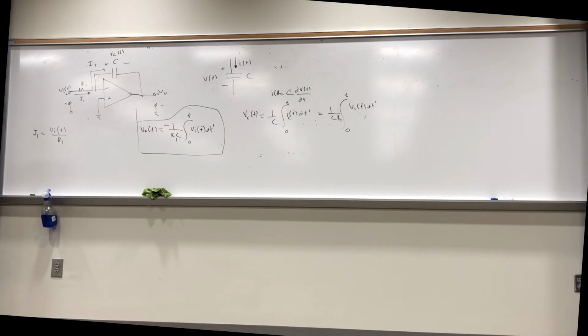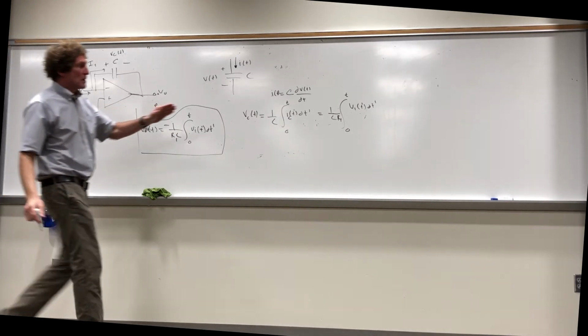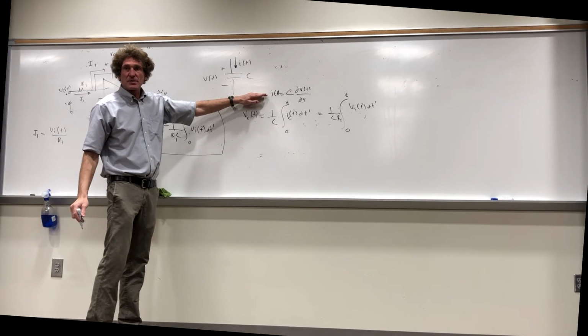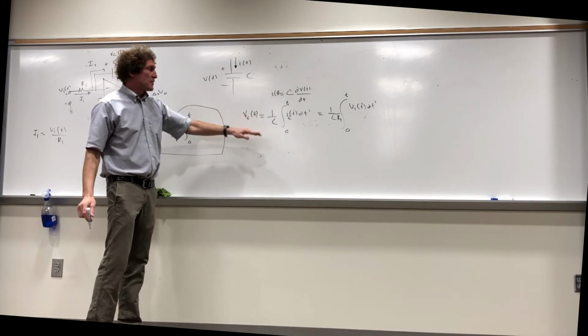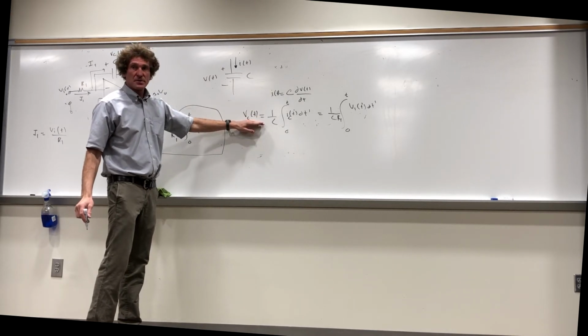Are you with me, class? How many see that? That integrates the input voltage. You do or not? It's pretty obvious if you understand this part, right? If you understand that differential equation, then you can find the voltage across the capacitor. And if you understand that, you know the voltage has to be negative of that if measured at V out.